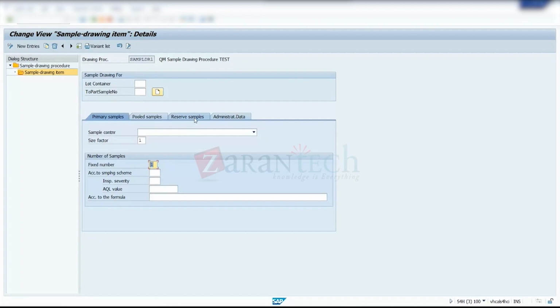For example, if there are 10 drums of chemical, and from each drum you collect one sample, or randomly from 5 drums, and you mix the samples, say 10 grams from each of 10 drums gives 100 grams, and you mix it and form a new sample, that sample is called a pooled sample. Mixing of multiple primary samples is a pooled sample. Clear?